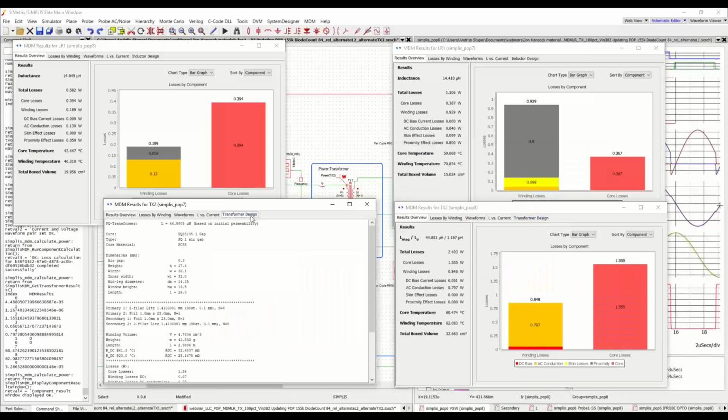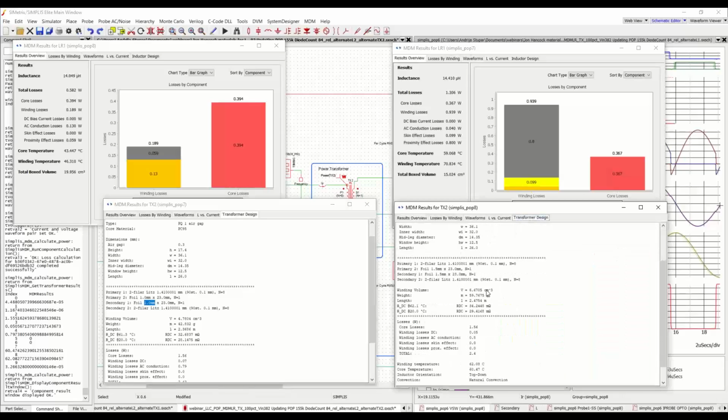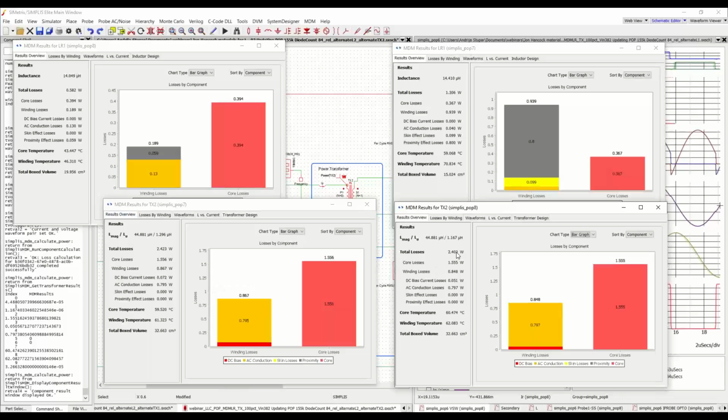And now, going from a 1 millimeter foil to a 1.5 millimeter foil, so increasing that foil thickness by 50%, has only gained us 20 milliwatts of improvement overall. And again, it's because we are increasing the length. So we're getting diminishing returns here, and you'll probably conclude that, taking into consideration cost and everything, going to 1.5 millimeter is really not worth your time.